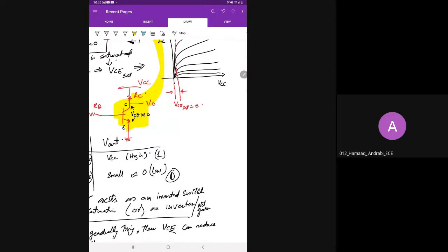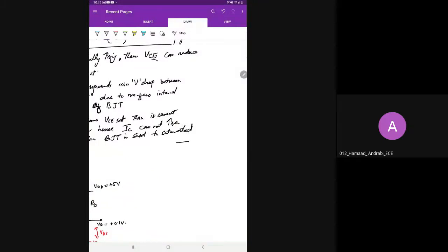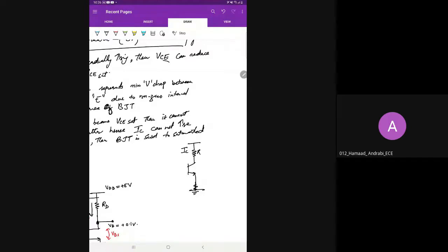you have basically this kind of transistor. I would like to comment on it. See, the transistor is like this. So IC is flowing here in RC. It goes into the collector, then comes back and exits through RC. When you have some potential drop here, which is V1, and some potential drop here, which is, for example, VCE, and you are pushing this transistor into saturation, VCE is further decreasing and going to the saturation value.